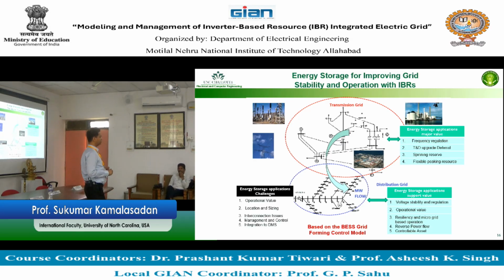So how do you connect the energy storage with the photovoltaics? I think we talked about it yesterday, I'm repeating it one more time. You can have an energy storage and the PV connected on a DC bus with one smart inverter. You can have multiple PVs connected to the DC bus, and at the end connect one energy storage again on the DC bus and then convert it to AC. Or you can have a bunch of photovoltaics in one area doing whatever they want to do, and on one bus, I'll connect an energy storage.